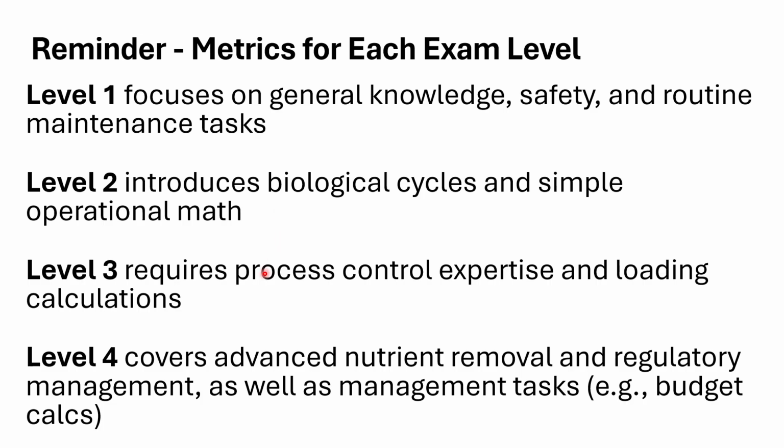Okay. Level 3, 2 words, activated sludge. And this one, they're going to want you to know process control and how to manage processes, how to troubleshoot processes, and they're going to want you to do loading calculations. They're going to want you to do disinfection calculations. They're going to want you to do what's called hydraulic calculations, pump calculations that we'll go over later, as well as calculate energy or electricity needed to run a motor, which runs a pump, which moves water.